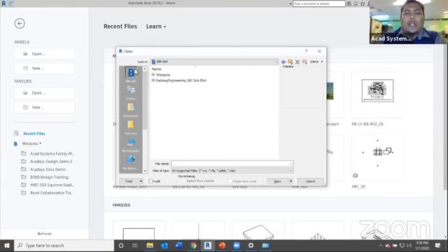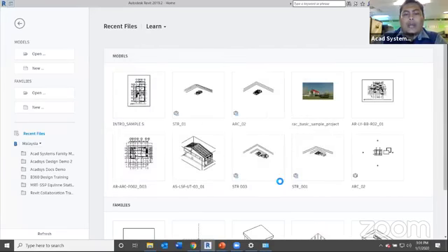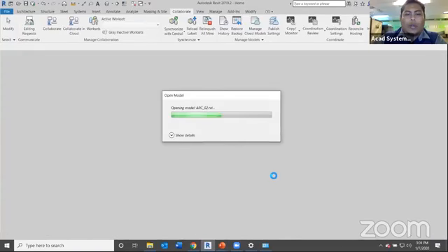Usually it has this folder automatically, or you can also download the BIM360 connector to work along with your local file. So I will directly find the BIM360 folders: Malaysia, Acadsystems, Acadsystems design demo, project files. Let's say I'm going to work on the architect files, and I will open this architecture file number 2, and you are actually opening this file directly from the cloud server. You no longer use your local server.